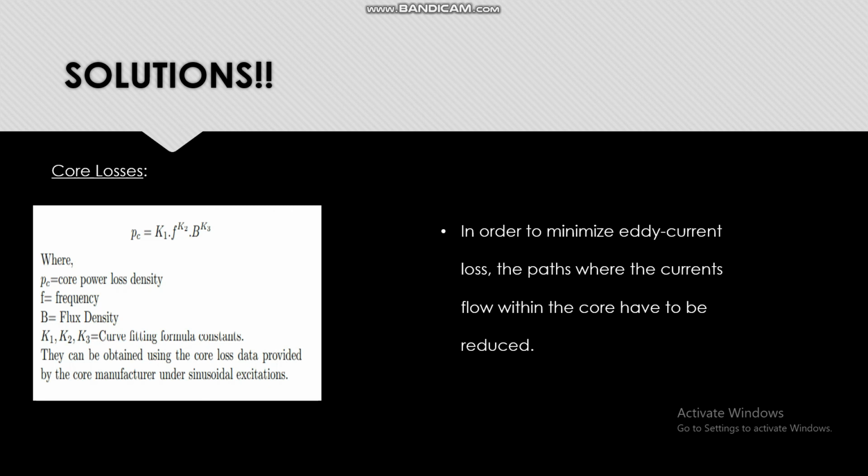High frequency, high power transformers utilizing power electronic converters are every now and again exposed to non-sinusoidal excitations. As we all know, the impacts of core losses in these transformers will be seen by broad arbitrary waveforms. This transformer core should work at higher temperatures brought about by more significant levels of power density and loss density. Hence, the thermal stability of the material is of extraordinary concern.